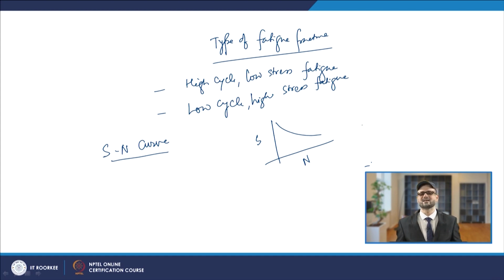That means that when the stress level is very small, below a certain limit, you can see that it is going towards infinity. It will go for a very large number of cycles, and that way you quantify or interpret the fatigue life of the component. That is how we discuss the fatigue strength of the material.